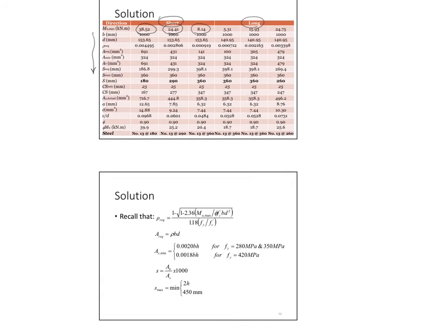These here are the equations that we used. Rho required, depending on the M ultimate that we had, and then we have the 3 G's here and the 3 B's over here. Rho required is calculated there. Then I go over As minimum for the slabs, which is the same for shrinkage and temperature.